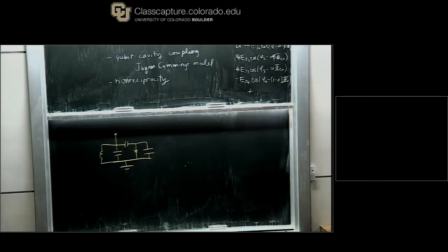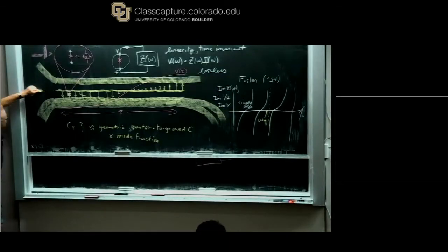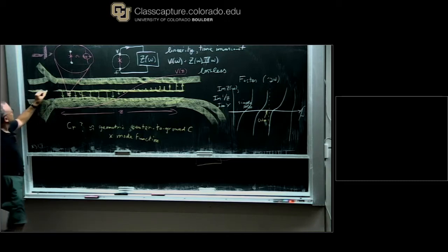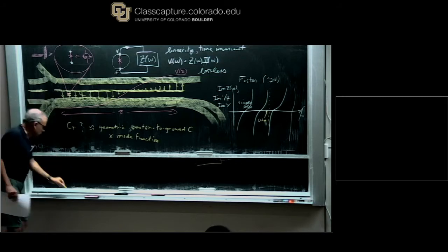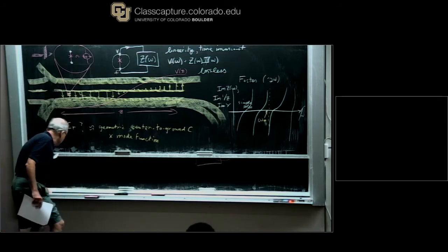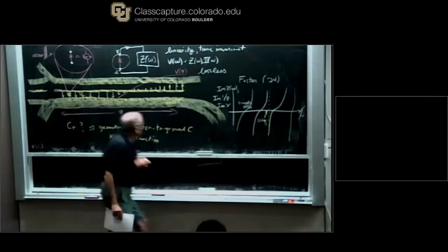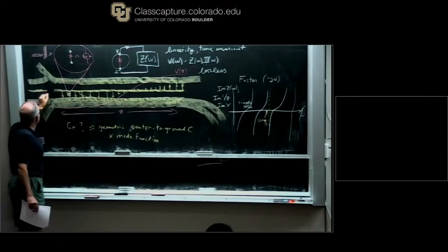It comes from the following ad hoc consideration, that typically this conductor ends, but then it starts again, and there's really a transmission line that continues, goes, say, to the edge of the chip, and then it's connected to whatever, your wires and your amplifiers and all that kind of stuff. And there is a capacitance here, from here to here, which we will give a phenomenological value. I mean, actually, you can also compute this. We'll call it C sub kappa.